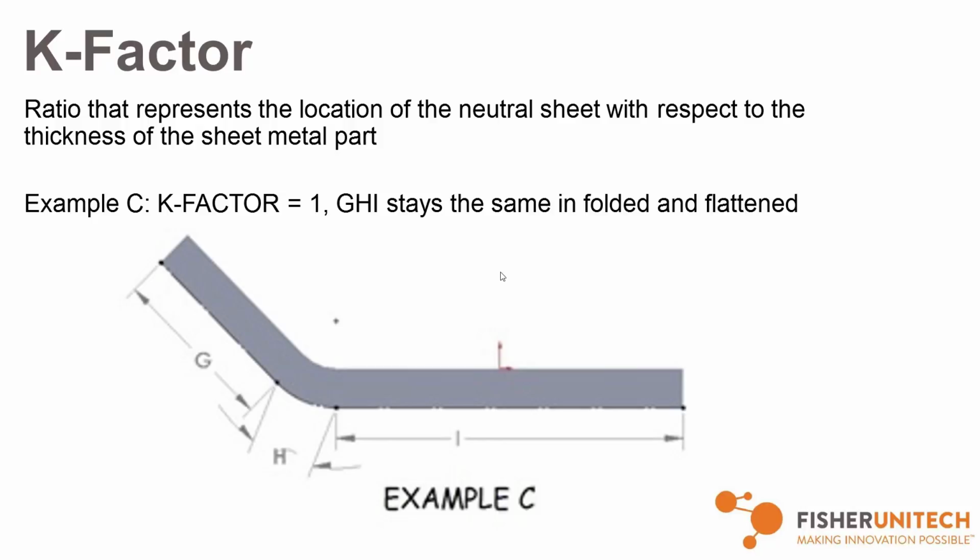You don't really have to change anything, even for your bend allowances, until you get beyond maybe 1/4 inch thick material. So if you can find those K factors, set them and leave them. Use them for the same gauge across the board up to about 1/4 inch. If you can't figure something out, we can try to assist with that as well.